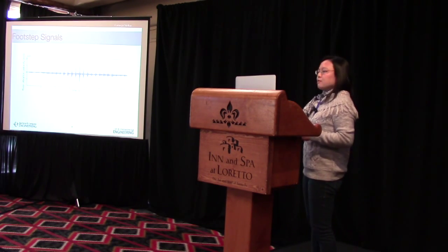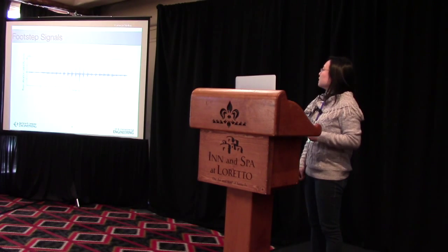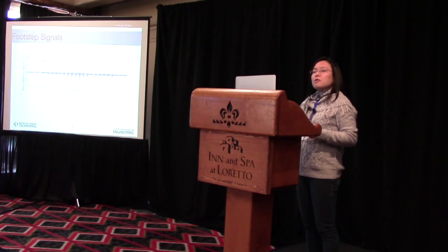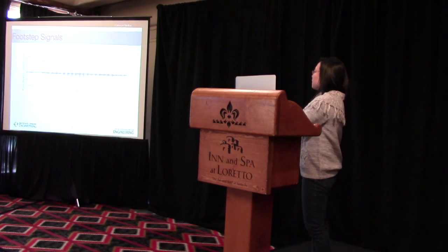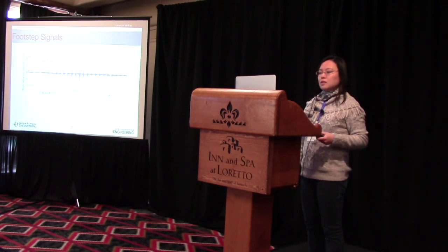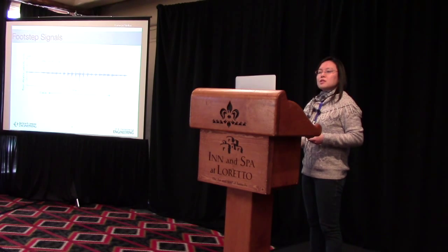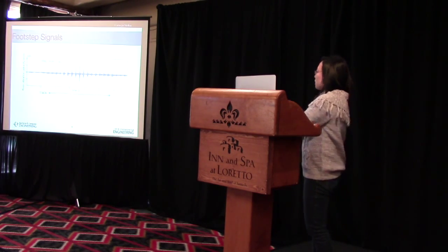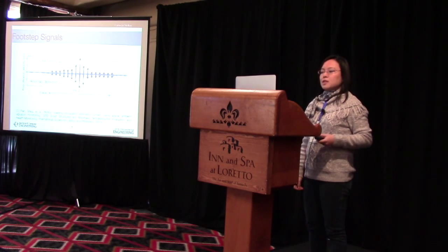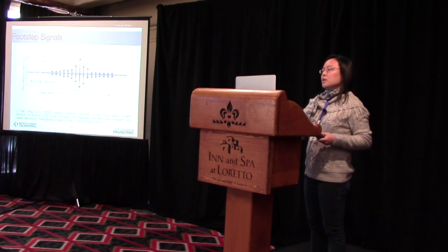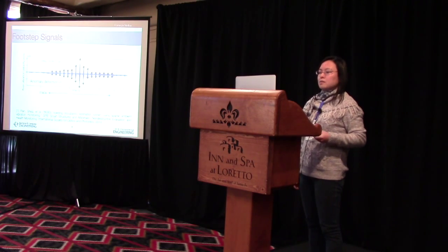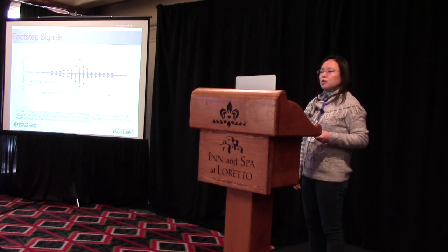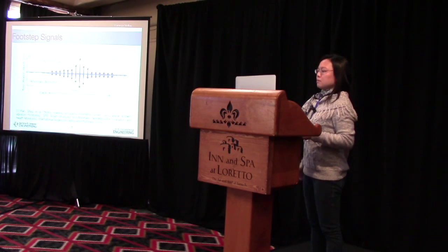We first define a step event as the floor vibration signal induced by a single footstep. And then we define a trace as a sequence of step events from a continuous walk of a person. In order to extract the footstep events from the signal segment for further analysis, we conduct anomaly detection based on the Gaussian noise model, as discussed in one of our prior papers.